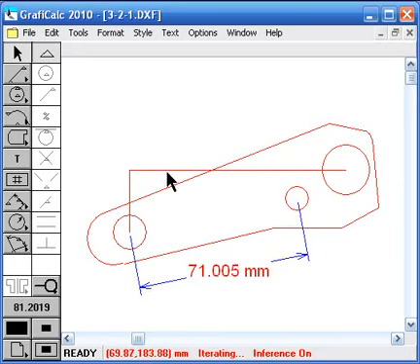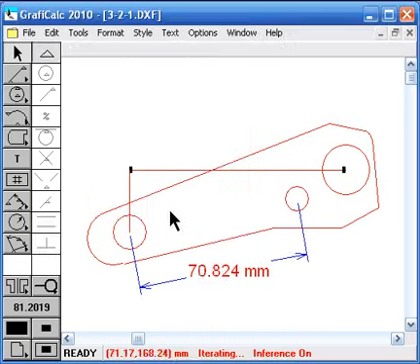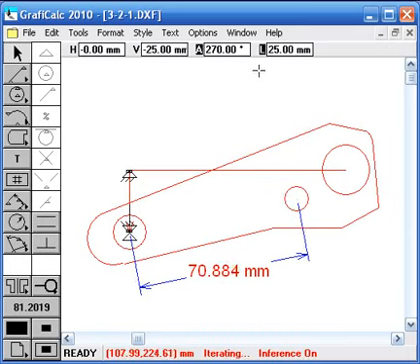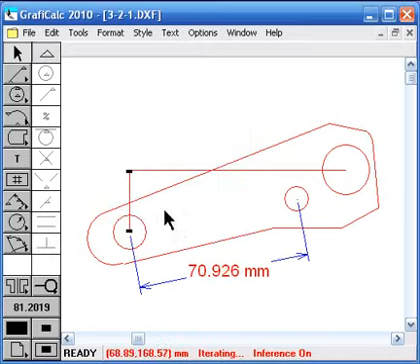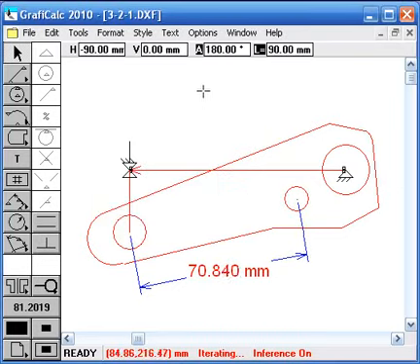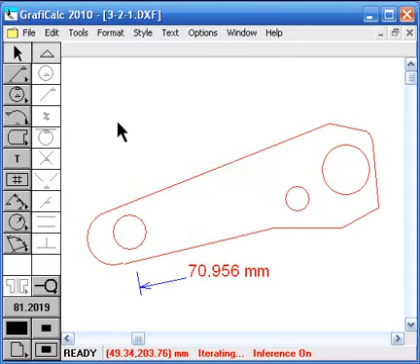Then he selects this vector, and the length is not going to be 90. The machine has a tolerance of plus minus 0.25 in its travel. I'm just putting these tolerances a little exaggerated to show the case. And likewise, this one also will have a tolerance. Notice the tolerance gets propagated, so you don't have to re-enter if the tolerances are the same over multiple vectors. And let's say this is also because of the fixture going to tilt by 0.1 degrees. Very well. So he has the simulation of the manufacturing process.